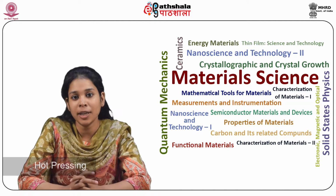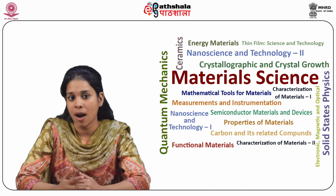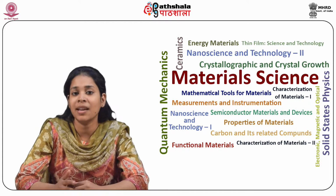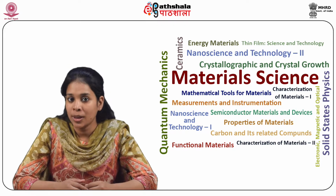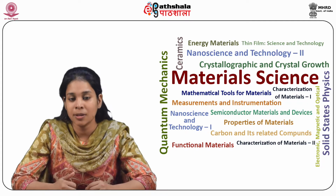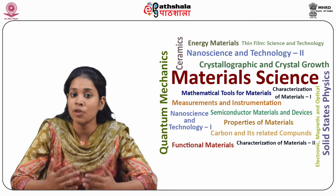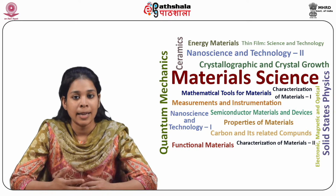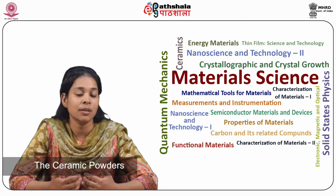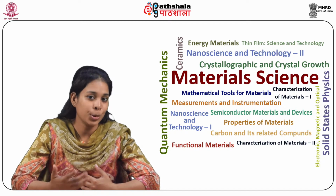In hot pressing, a uniaxial pressure is applied to the parts during sintering. The pressures used are 10 to 70 megapascal, but it can exceed 200 megapascal in rare cases. The piston and the mold have to be made of a material capable of withstanding stresses at high temperatures. In this case, graphite is the most used material for this purpose because of its high strength, which increases with temperature, and graphite can be easily machined and shows no reaction with the ceramic powders. However, graphite can be used only in an inert or reducing atmosphere.